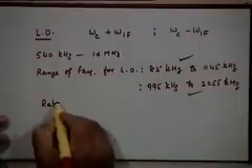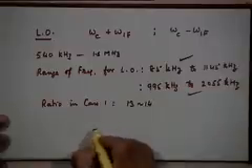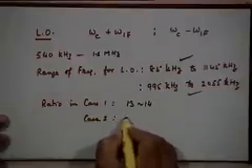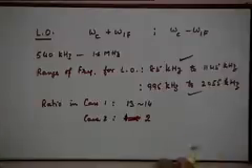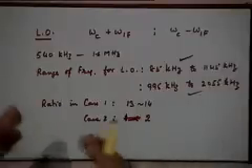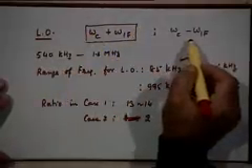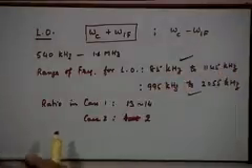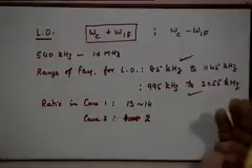So the ratio in case 1 of the two frequencies is of the order of 13 to 14, whereas in case 2 it is basically of the order of 2. It's much easier to design oscillators where the tuning range, or the variable frequency range, has a smaller ratio than a much larger ratio, and that's why typically you go for the higher local oscillator frequency rather than the lower one. That's in fact the reason why it is called a superheterodyne receiver. Heterodyning is mixing, but you are mixing with a local oscillator at a higher frequency, and the name superheterodyne comes from there. Besides, if you wish, you may say it is superheterodyne because it does a superb job, but that's not the reason.